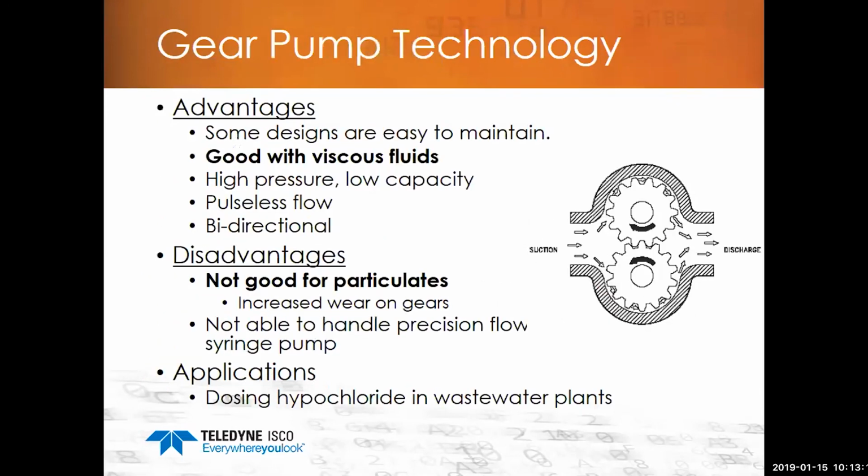Looking ahead, another type of positive displacement pump. You've got gear pump technology. So this is very simple. It's just 2 wheels, 2 gears moving and pulling fluid in, pushing it out. And it's good with viscous fluids, but if there are particulates in the fluid, that's going to wear away the metal or the plastic on the gears. So again, this goes back to when you're designing the application, look at the fluid that you're using, look at how fast it's going to move, look at the viscosity of it, and you can kind of pick and piece which types of these technologies you would want to use.